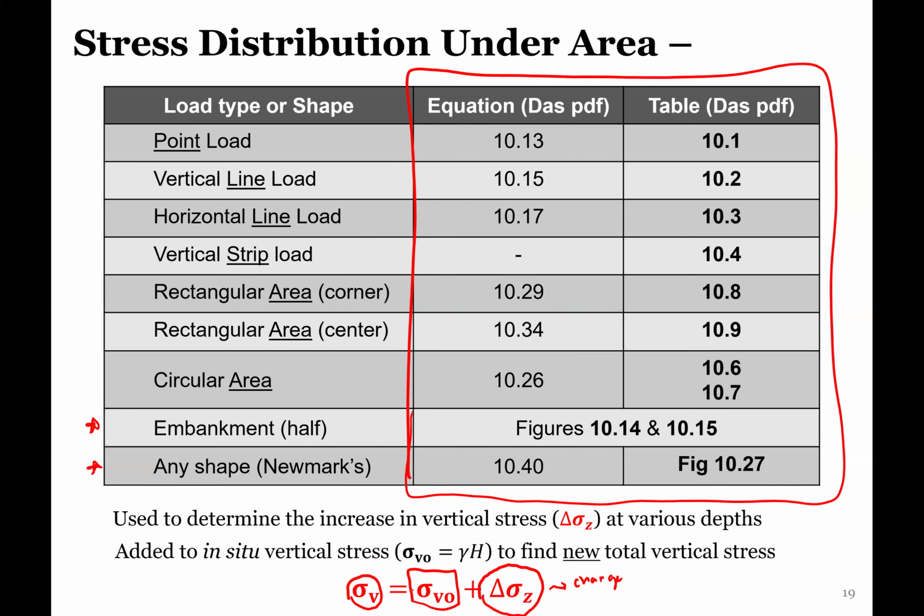So next class, what we're going to talk about is a specific type of problematic soil that we see a lot of in Florida, and that's going to be our organic and peaty soils, which are highly compressible. And one of the things that we can actually do is utilize this increase in vertical stress to induce settlement before we put our structures on it. So this is a process called surcharging. I'll go over that, and we're also going to talk about soil sensing too.